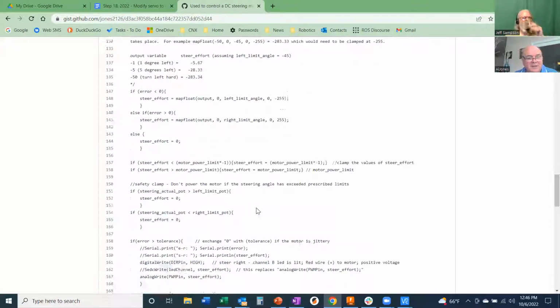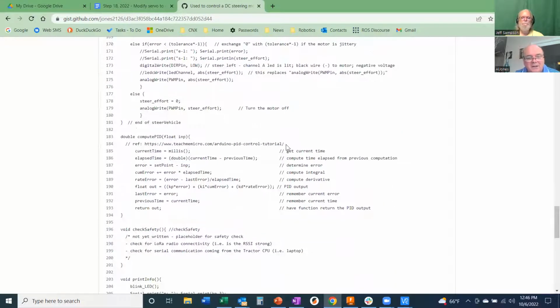So that's where it came from. It didn't come from, hey, I'm getting a noisy potentiometer. The reason people put averaging on that is because A to D converters can notoriously be noisy trying to read whatever value you want, and that's why it was on there in the first place. You probably will need that, but I don't know that just plotting it out to see what it's doing will give you an idea if your pots are noisy or not.